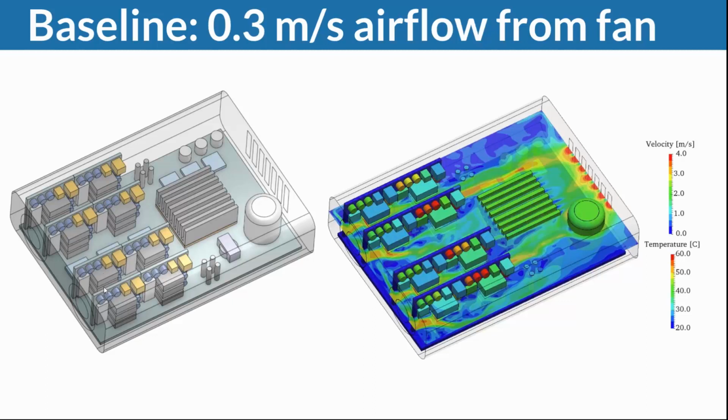Inside this air domain, we're simulating convective heat transfer. The air is being moved in from the left through the fans, and then it flows around these solid components, takes on heat or takes off heat from these solid components and moves it out, while at the same time, we're applying different heat sources, the wattages we've seen in the beginning.